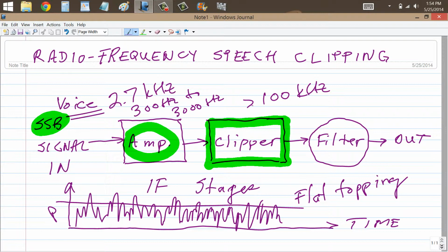You'll hear the ordinary voice, and then either side of that voice, those flat top transitions, those abrupt corners on the clipped wave will produce this crackling sound. You may have heard that kind of splatter. That's in fact what it's called, and that's a pretty good name for it. It pretty well describes what it sounds like. Sounds almost like rain falling on a pavement or something like that, splattering. And it is a mess, and it's also illegal. The Federal Communications Commission here in the United States frowns upon a signal that has that characteristic.